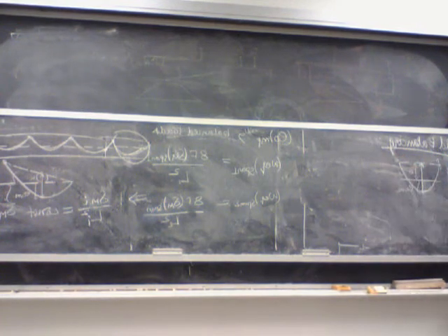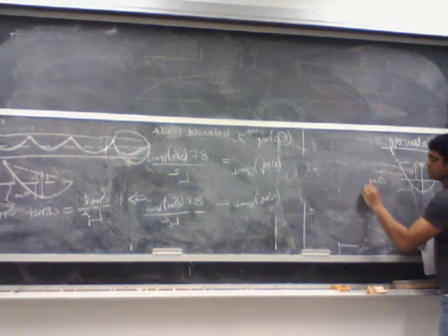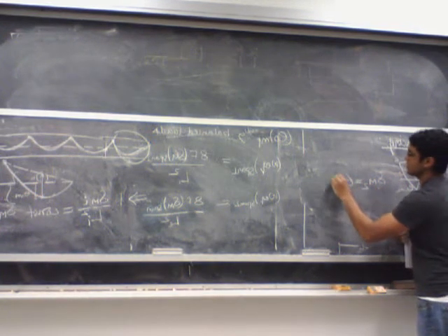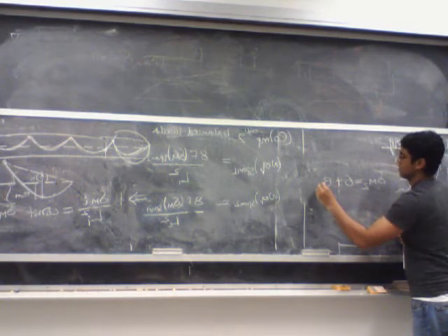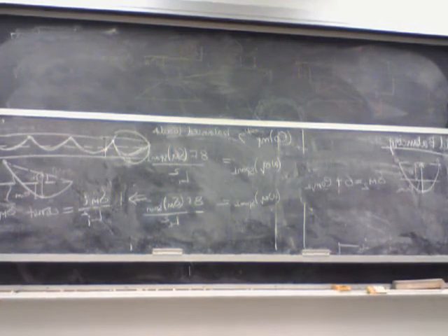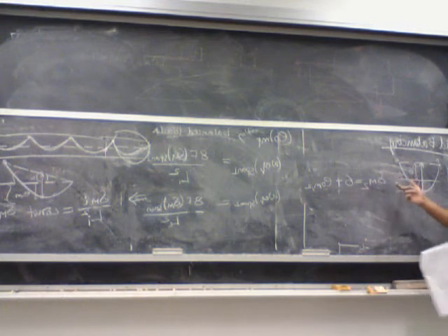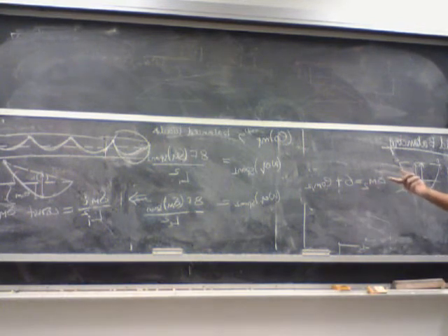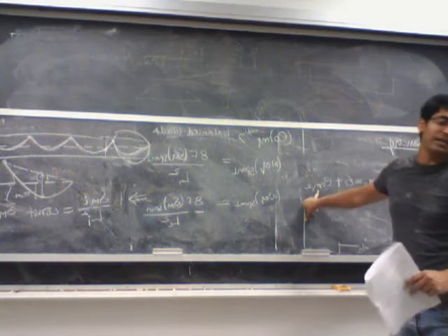So this actually becomes 6 inches. So delta M for span 2 is 6 plus E naught m of span 2. So now what I have is an equation which correlates delta M for two spans with their corresponding eccentricity at the mid spans.